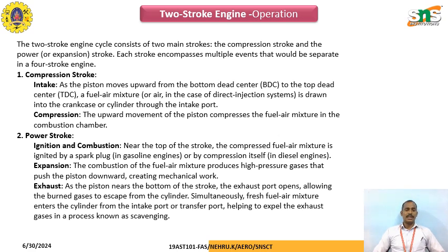Compression stroke, intake: as the piston moves upward from the bottom dead center to the top dead center, the fuel-air mixture is drawn into the crankcase or cylinder through the intake port. Compression: the upward movement of the piston compresses the fuel-air mixture in the combustion chamber. The second, power stroke, ignites and combustion takes place. Near the top of the stroke, the compressed fuel-air mixture is ignited by the spark plug.